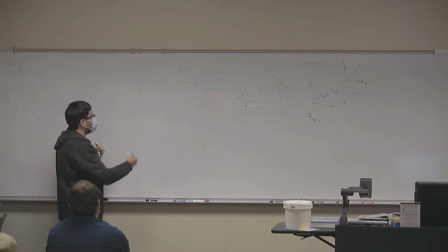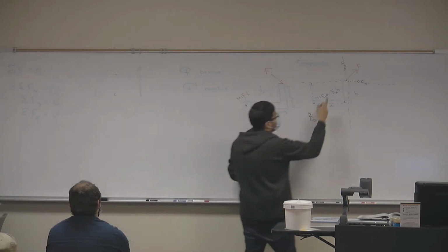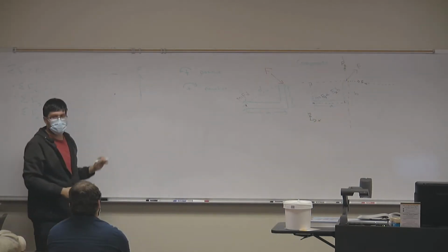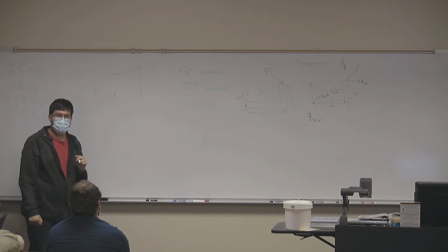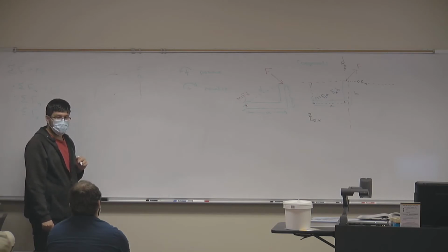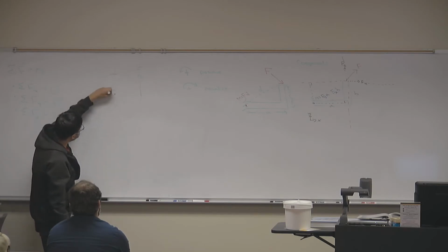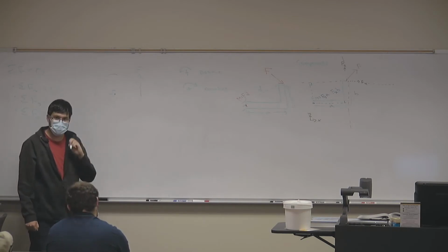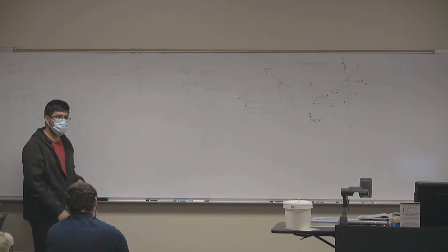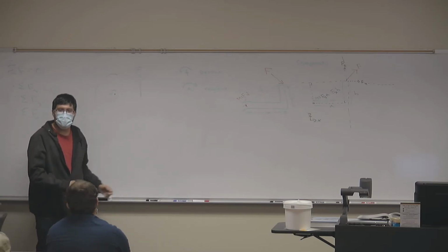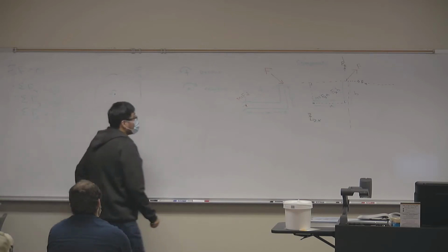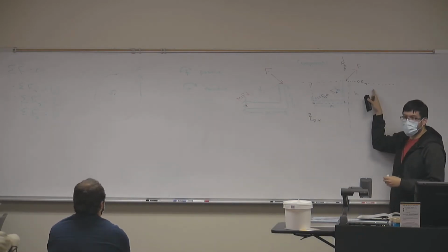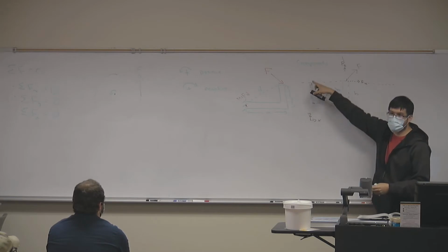Now if I apply a force vertically upwards to the right of my steering wheel, in which direction am I steering my wheel? Counterclockwise. There we go, counterclockwise, right? So is this a positive moment or a negative moment? That'd be positive. Good. Does that make sense to everyone? If it doesn't, then do your best, right? But I like to look at it this way because now, if we look at the x direction of force, we have a force being applied on top of my point.